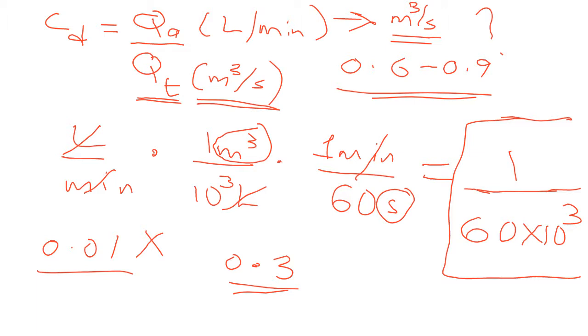This is too small. And for the height of the channel, I told you clearly, do not use a ruler to measure the height of the channel. Use the depth gauge. When you use the depth gauge, it will give you 95. When you use a ruler, it will give you 120.